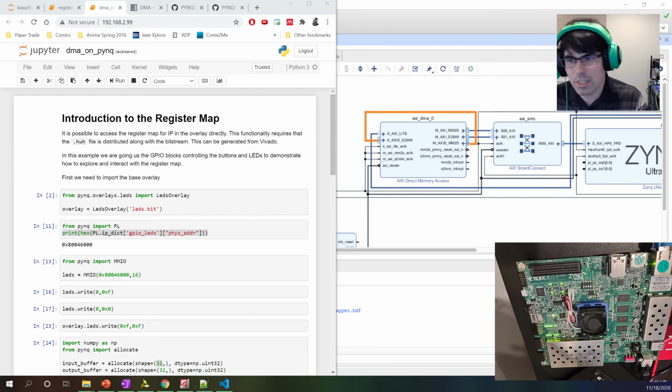I'm just thinking, PYNQ runs on a bunch of these really complicated, really expensive boards, right? But PYNQ is super powerful. If we could define that for LiteX, get LiteX running Linux, we could get that working on a Lattice board, or on probably a cheaper Series 7 board, like an RD board. I'm going to ask the people who do LiteX, and maybe look at their software.